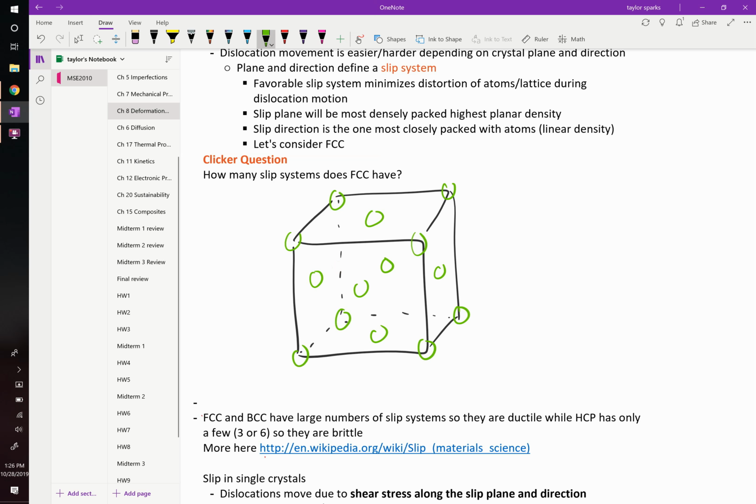Now you guys tell me, what is the most densely packed plane in this structure? The most densely packed plane. Is it obvious? One of the faces is a good guess. That's not the most densely packed. Yeah? Would it be the 1-1-1 plane? It is the 1-1-1. What does the 1-1-1 look like? The three corners that make the smallest pyramid. Yeah, we could draw it.